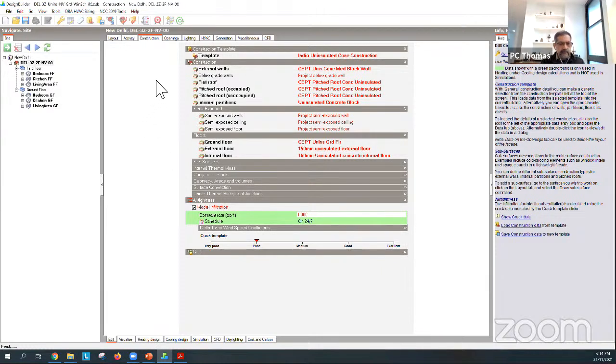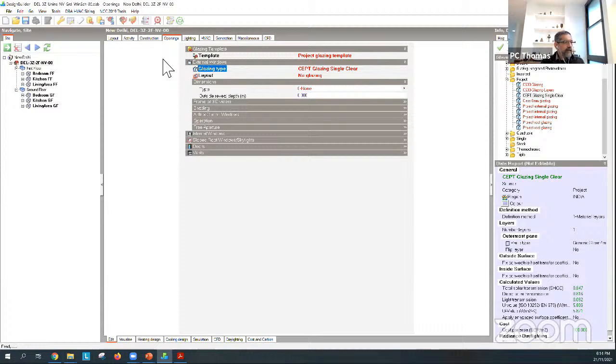Then the last thing, well, one of the last things really, is if you go to the openings tab, what you'll find is that once you switch on the natural ventilation calculations, you will get an additional item here under Windows, okay? And that additional item is called operation.